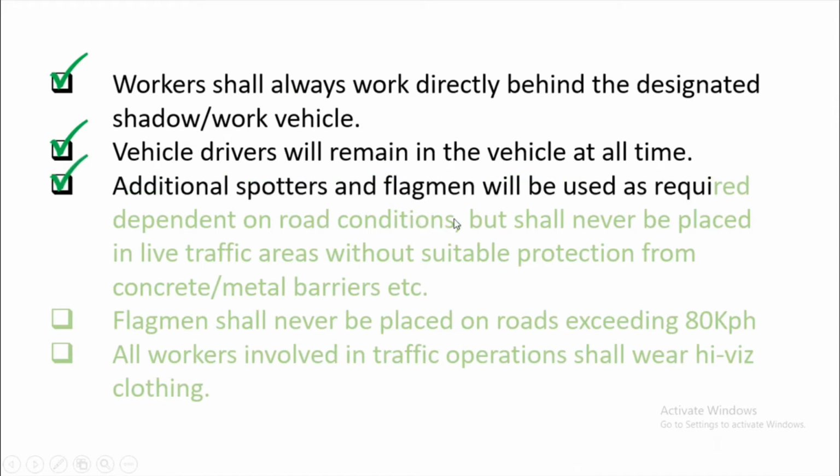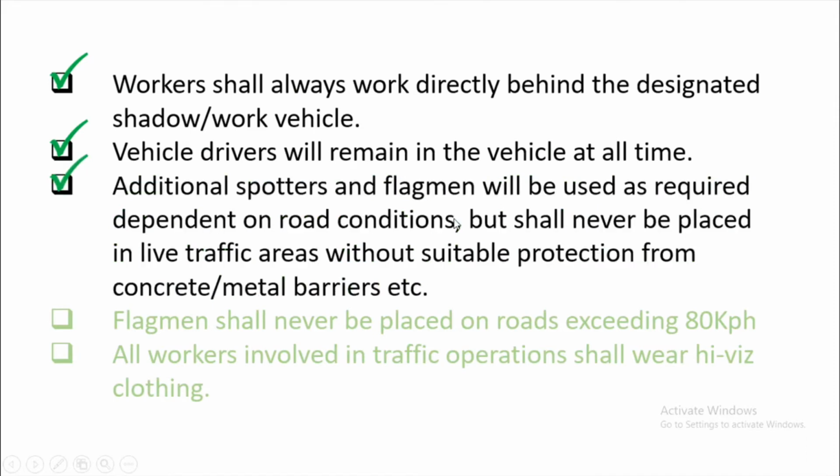Additional spotters and flagmen will be used as required dependent on road conditions, but shall never be placed in live traffic areas without suitable protection from concrete, metal barriers, etc. So in the traffic condition that there's a need of spotters or flagmen, make sure that we provided additional spotters, but make sure that they are protected with the concrete barriers and metal barriers or any types of hard barriers.